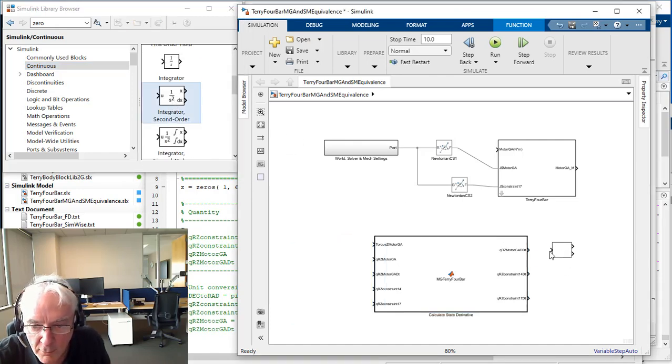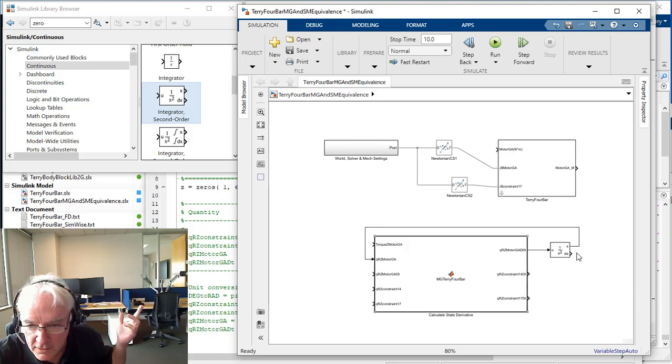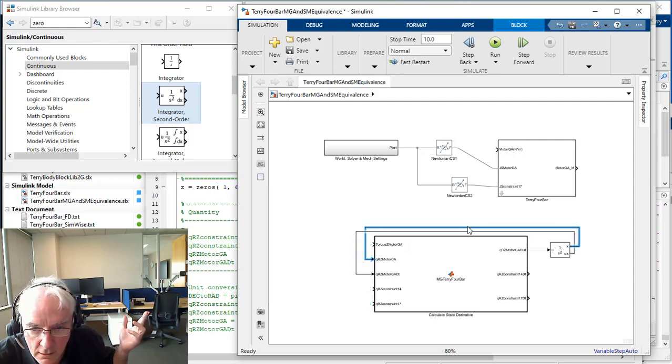And our motor angle is kind of operating at the acceleration level, so second order integration is required there. And so this block is super efficient at doing both the first and second order integration, so it's a good idea to use it. Let's say I want to just confirm dx goes into dt and x goes into the angle itself.